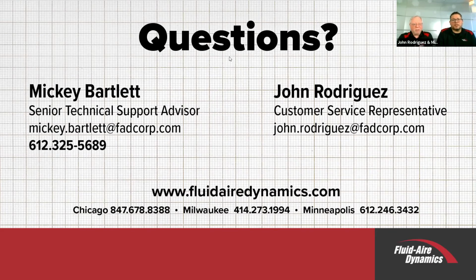There's another question here about mist eliminators versus SPE filtration. I think we could probably do an entire day on that. Well, you can, but I have my opinions. Some people don't agree with me. A mist eliminator is a very large device and a very expensive device. Unless the power company's going to pay for it, I personally don't think they are worth the money. That's my opinion. They are usually a 3 micron filter. And remember, I said I like to get my air as clean as possible, down to 0.01 micron, so you will need a filter after it anyway. In most cases it's just another place to spend money. That's my opinion.